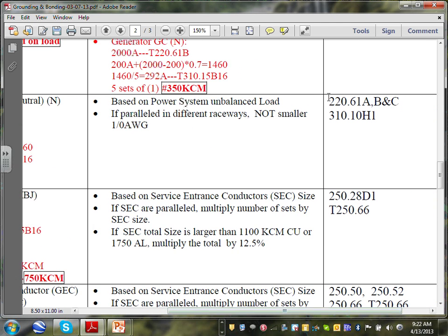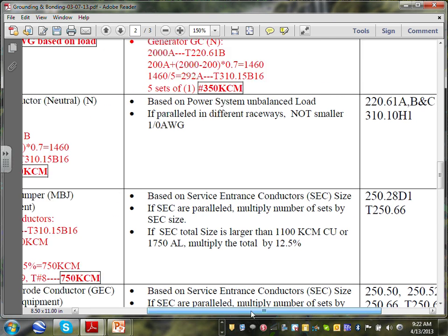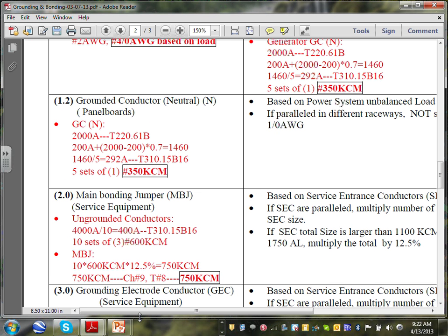And here's your requirement here in the NEC code book. So unless you go and get rid of everything 3-phase and size it based on that size, I typically, when I have a sub panel, this is my method. When I size a sub panel downstream, I take advantage of 220.61(B), guys. So you take the 2,000 amp size of your panel. The first 200, leave them alone. That's from 220.61. Anything higher than that, the code allows you to chop them by 0.7.